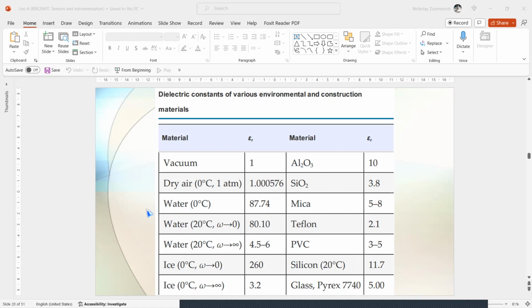Even at temperatures above the dew point, water vapor might condense due to contamination. It may be hygroscopic particles that attract water molecules and act as condensation nuclei. This means that for the highest performance, the temperature of the sensor should be kept well above the dew point temperature.